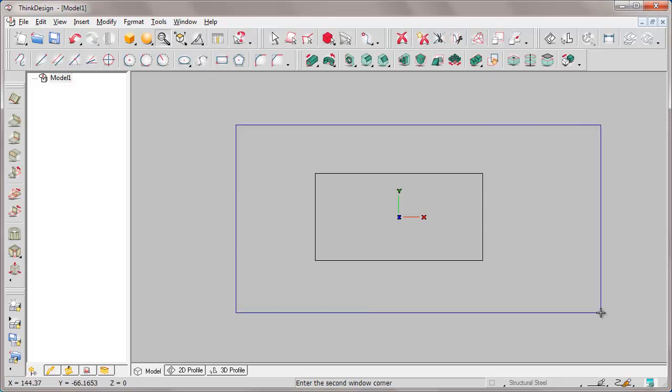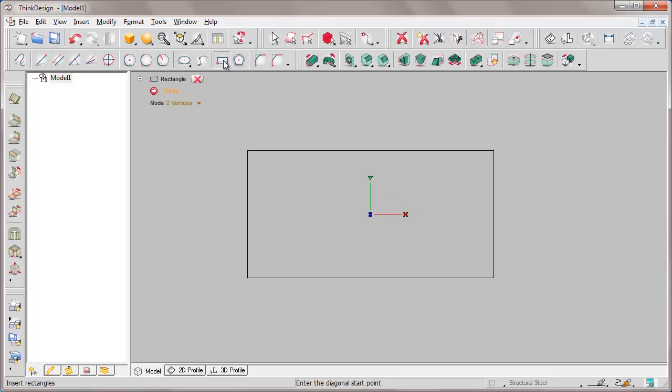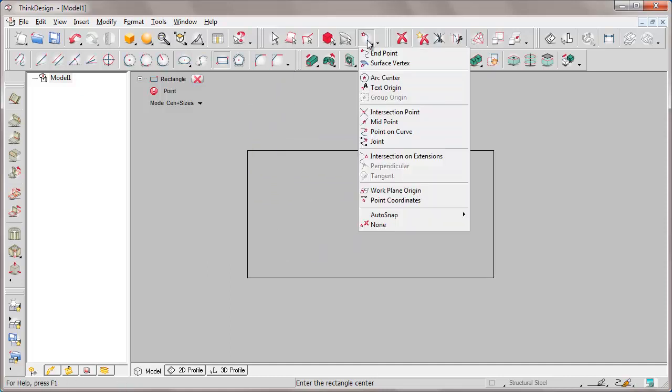Let's make a zoom window now, because we are going to draw with the classic approach of 2D drafting, which means we draw geometries directly with the size of the design, as in this case a rectangle, where we enter 15 for X and 15 for Y, and we position it in the work plane origin.